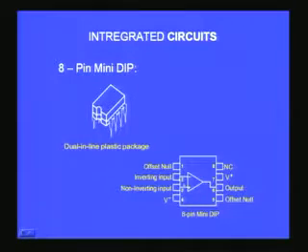So you can see here the corresponding pin diagram. These are all usually from the top view. So you have 1, 2, 3, 4 from the top. You have to look at this, and to identify that usually you will have an indentation here. That is what is shown here, a small cavity. That cavity will come at the top here, and that shows that to the left of that is 1, 2, 3 when you look from the top side.